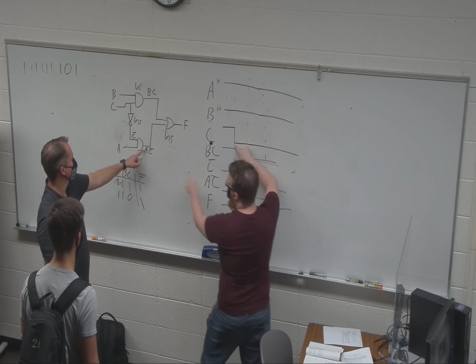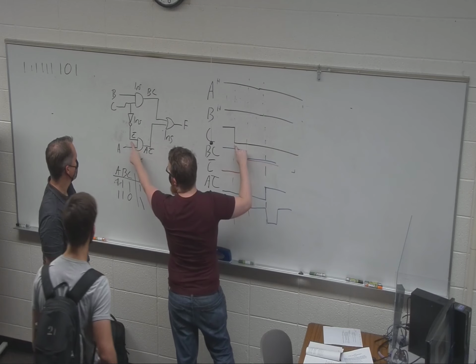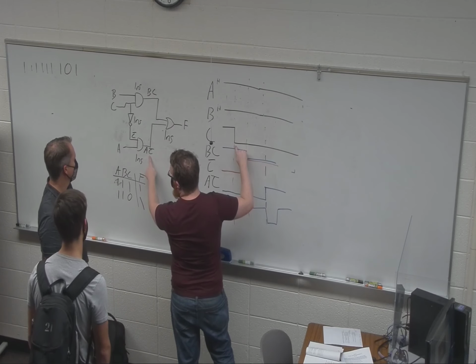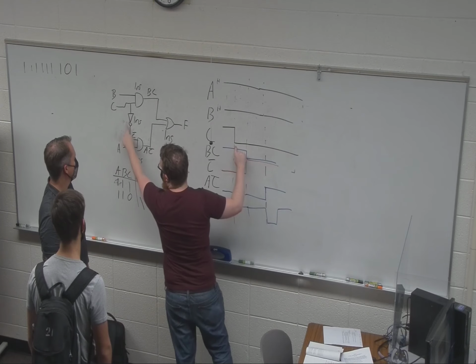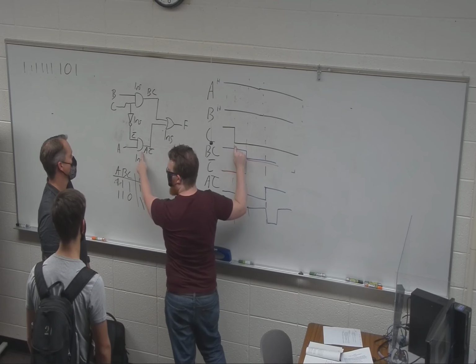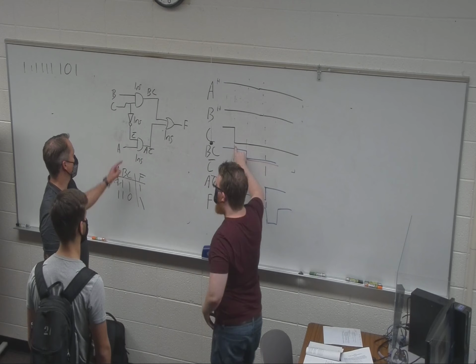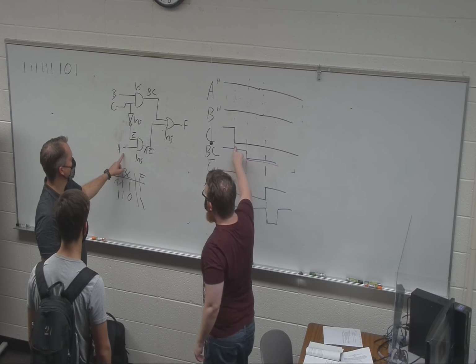Right here. So then 1 nanosecond later, this gate responds. It takes 1 nanosecond for this wire to this gate to respond, and 1 nanosecond for this gate to respond, because it's high, low.